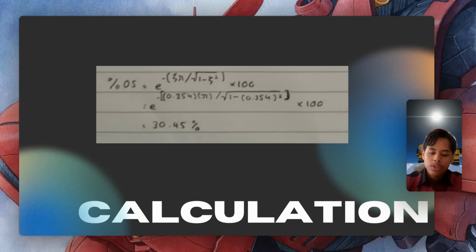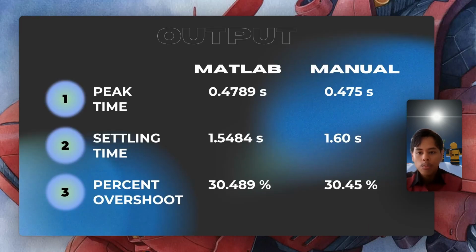And percent overshoot indicates how much the response exceeds its final value before settling. Our calculation gives an overshoot of approximately 30.45%. And this is the output comparison between MATLAB and manual calculation.